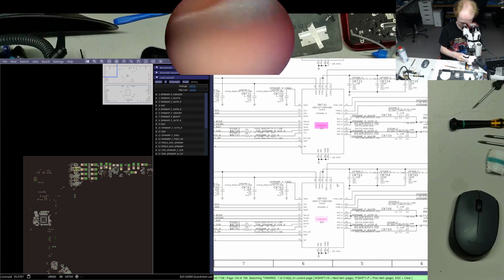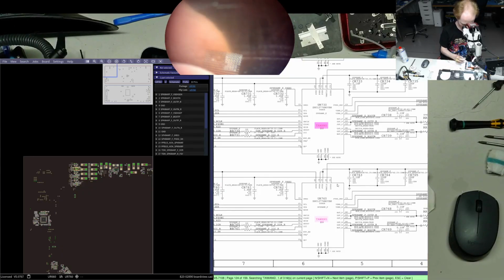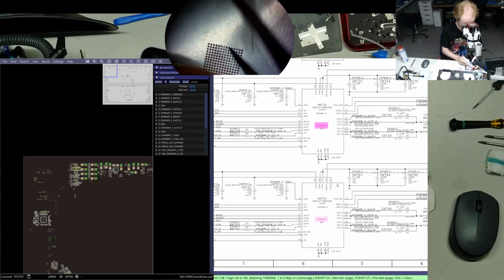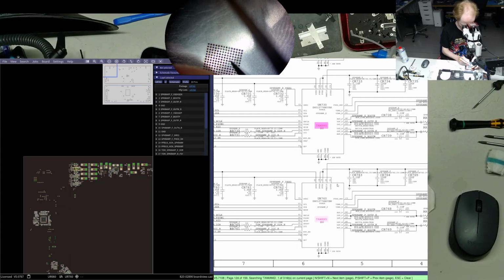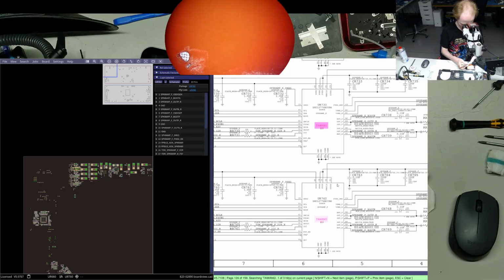But I remember times buying LP8550, the LED backlight on MacBook Airs, like Intel MacBook Airs, just to save some time reballing it. But basically you saved some time, then you had to flash it to get proper brightness control. So it wasn't really that time saving, because you just moved your time somewhere else.